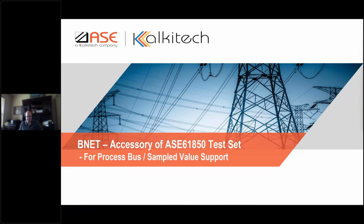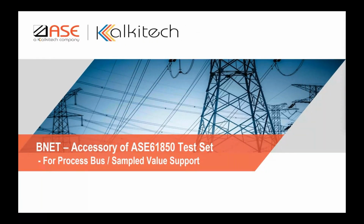Sterin, you had mentioned process bus. For maybe some of the new folks out there like me, can you elaborate what exactly is a process bus? Earlier, the CT and PT signals were wired directly to the protection relays, and with 61850, they are trying to digitize that part. Here, by process bus, we mean the communication from the CT and PT, like current transformer and voltage transformer, to the relay. That part has been digitized, and there will be a separate network that connects from this CT and PT to the relays. We refer to that network as the process bus. All right, okay, got it.